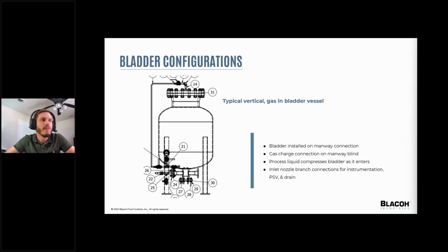Hopefully this webinar will give you a realistic picture of that and highlight some of the limitations of each type, help you understand a few different configurations, give you some design considerations to help you select and specify a vessel for your application. So to begin with, we'll look at this hidden view drawing of a typical vertical gas and bladder vessel.